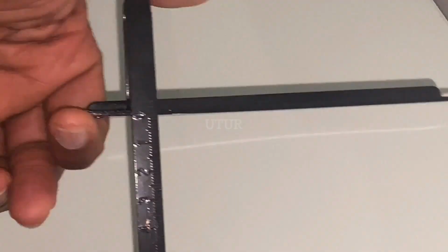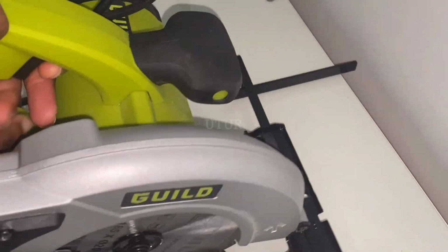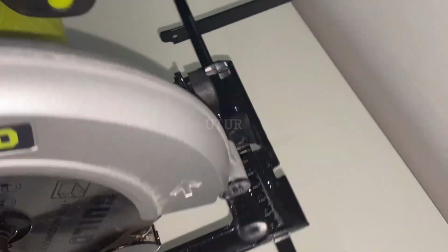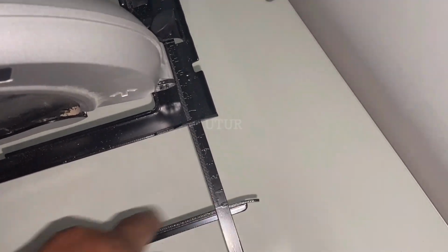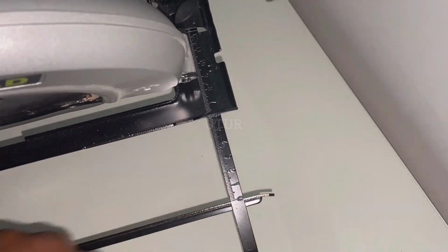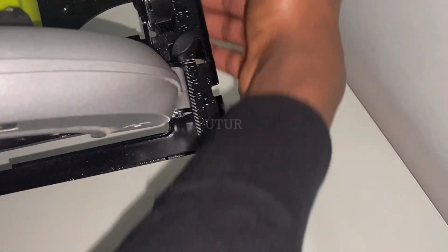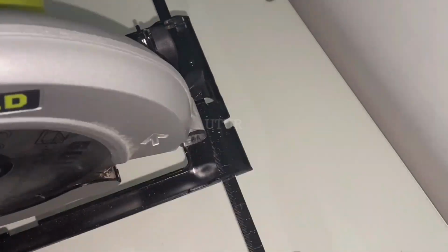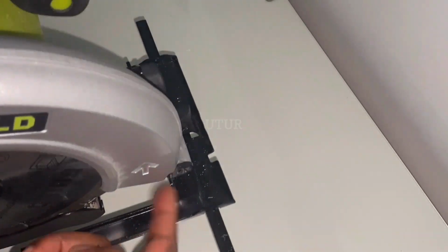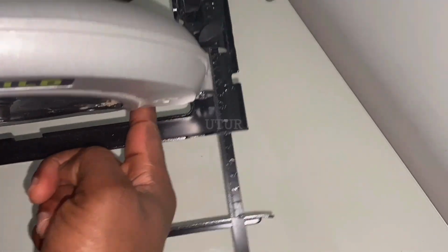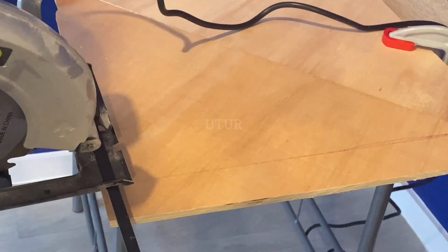Irrespective of which side of the board you're cutting, if the edge of the board is curved or warped, then your rip cut will be off by the same amount as the edge of your board. I can't stress it enough, the edge or the side of your board should be as flush as possible against the rip fence or the parallel guide. This parallel guide enables you to make narrow rip cuts, but if you want lengthier or larger rips, you could deploy the use of a parallel guide extension.